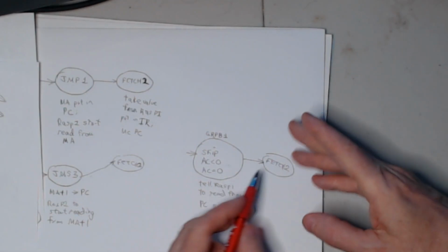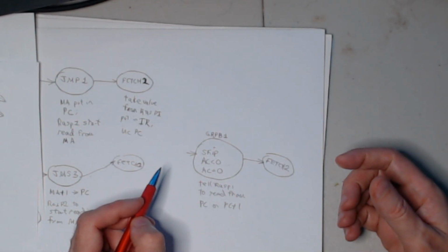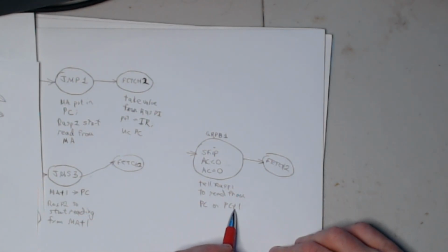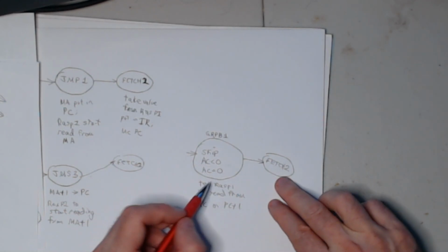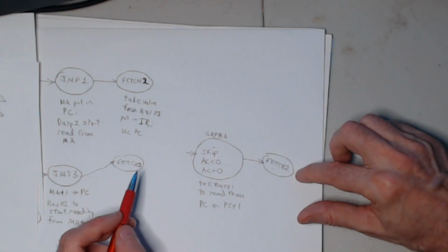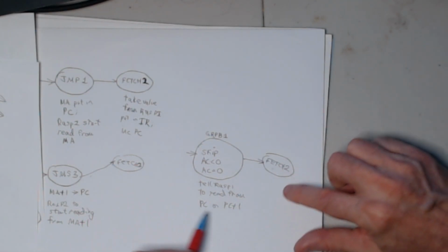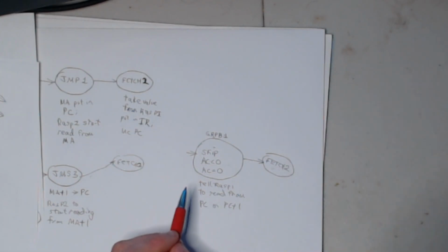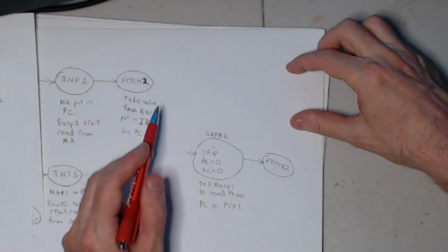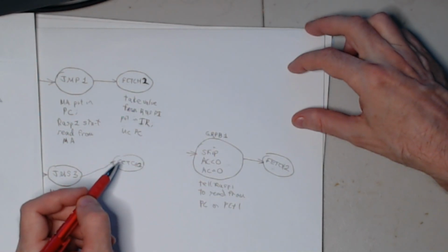Okay, because in the next cycle the Raspberry Pi is going to say, okay, here's your opcode. This thing has to decide, by the end of this cycle, whether or not it's skipping, and increment the program counter by 1 or not. And then fetch 2 is going to come back with the opcode that you read from either PC or PC plus 1. So these are just optimizations that it can do to save a clock cycle.